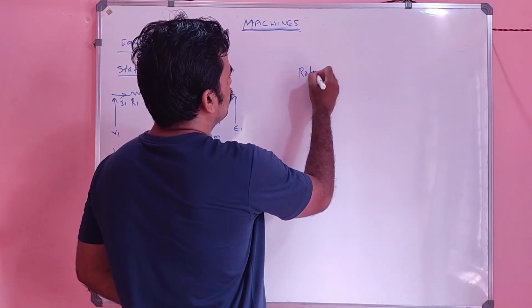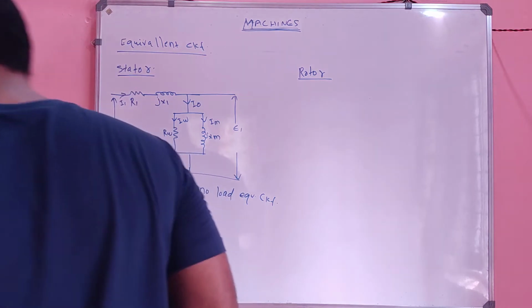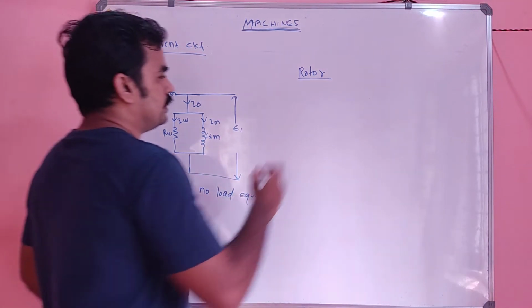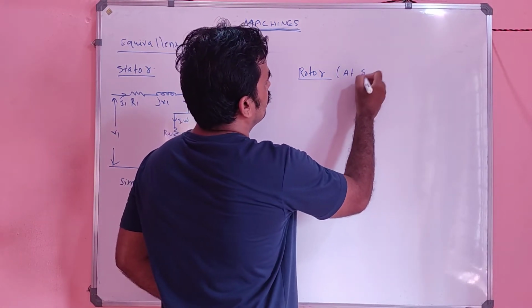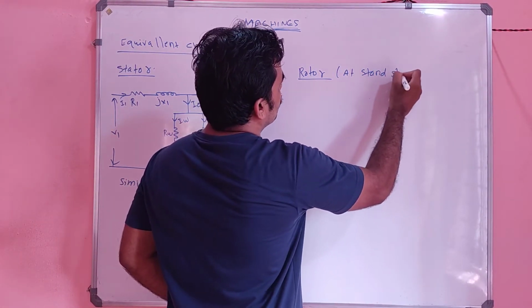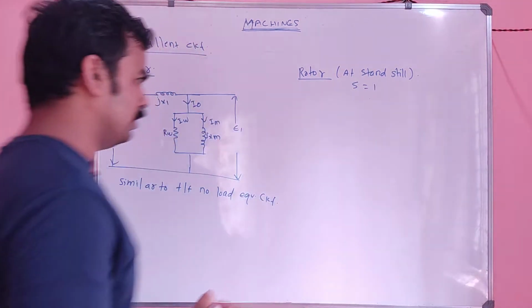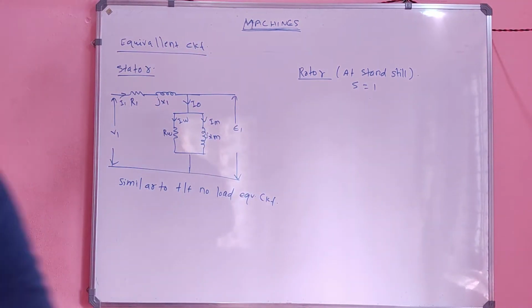Next you have to go for the rotor side. So, rotor at standstill. At standstill means, my dear, S will be equal to what? 1. Correct?